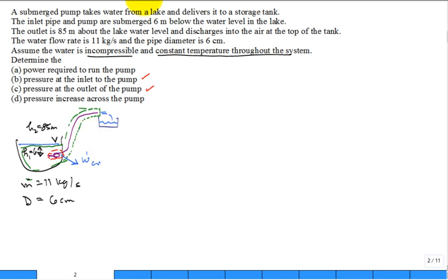And we write the first law for that control volume, and we'll get W dot CV is equal to the mass flow rate of the water times the inlet enthalpy minus the exit enthalpy, and then we have the changes in the kinetic energy, 1/2 V1 squared minus 1/2 V2 squared, and then we have g (Z1 minus Z2), the change in the elevation.